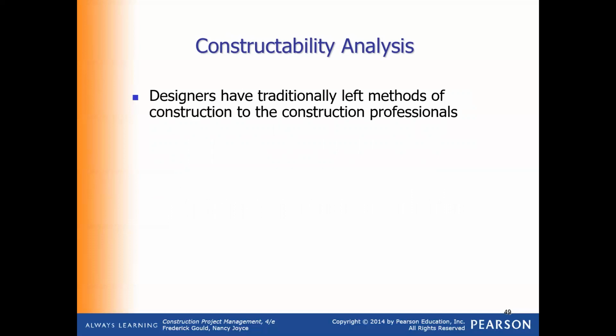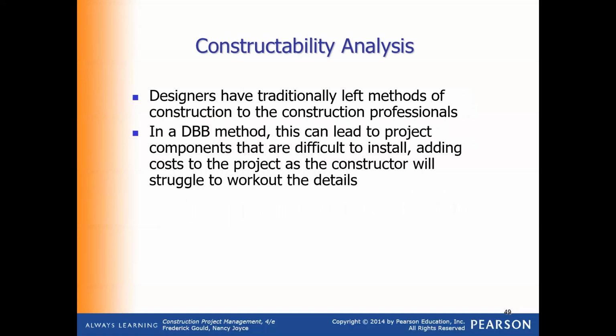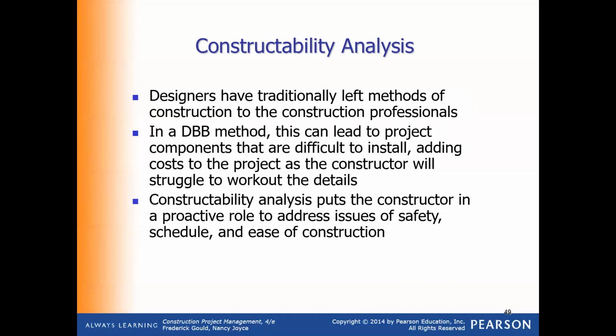As far as the constructability review, again, a constructability review is very powerful, and that's why we always promote for constructors to be involved at an early stage of a project during the design phase, if you will. And the traditional method is always the construction means and methods are left for the contractor to figure out during the construction phase, which leaves them under a lot of struggle because the architect just came up with the design and it's all left for the builder to build it. So in the traditional method, which is design, bid, build, this is the case, which is not very effective.